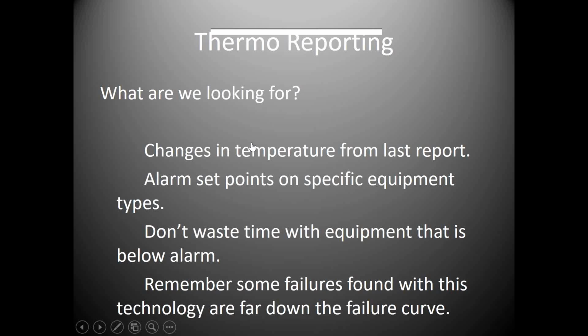Just remember my last comment on thermography. Thermography is an excellent technology, but if you think about where you're going to see those failures on your PF curve, they're going to be down closer to the bottom where we could actually touch them, where we get close to the human senses. But again, an excellent technology for electrical, excellent technology for mechanical, because we see things at a very early stage. So I don't want you to misinterpret that it's not a good technology, because it is, but it's farther down the failure curve when you find the failures.